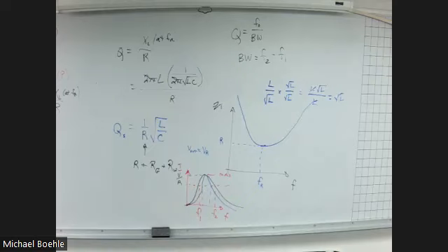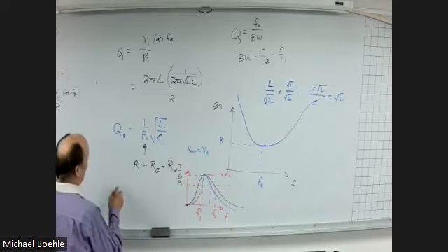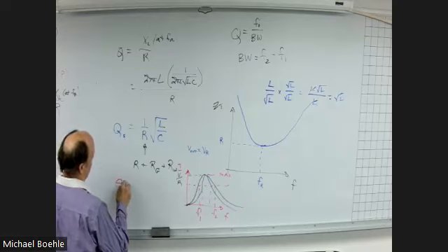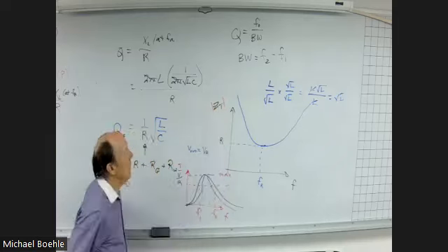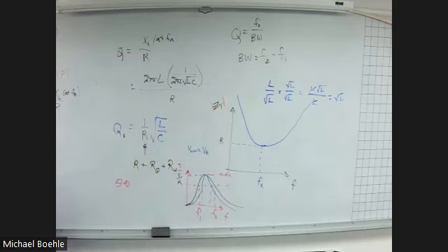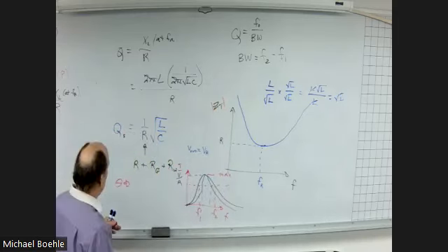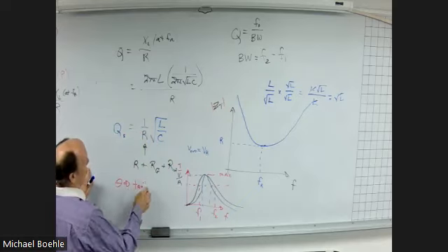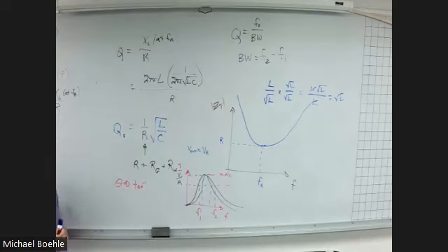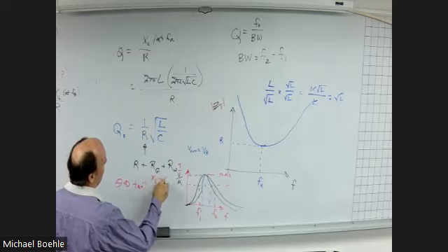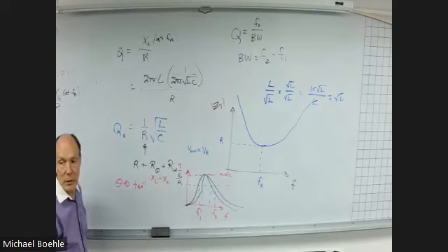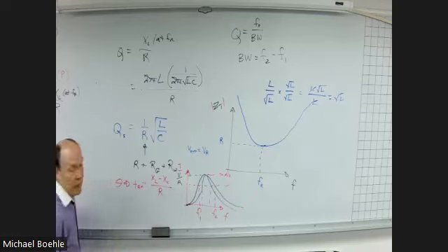Now I focused on the magnitude of the impedance. What about the phase shift? So when you look at the total impedance, that's the magnitude of it. And I talked a little bit about the phase shift, because the angle of the impedance will of course be the inverse tangent of the total reactance, which will basically be what? The inductive reactance minus the capacitive reactance divided by R, right?